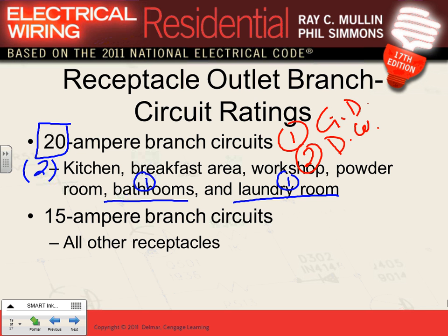Microwave. Thank you. We're coming to another one. Microwave, these are the ones that are also recommended. Highly recommended microwave, you put it on a 20 amp circuit. Are we missing anything else? Sump pump. If you have a sump pump, highly recommended. Actually, you have to. Sump pump is a dedicated load. You have to put it on a 20 amp circuit.